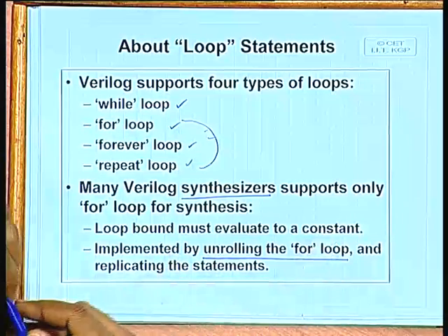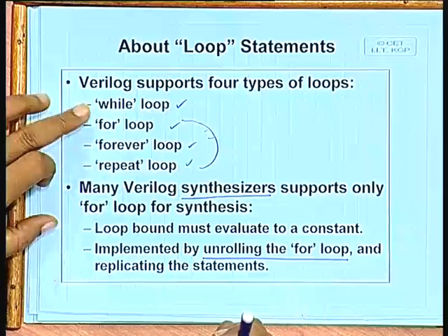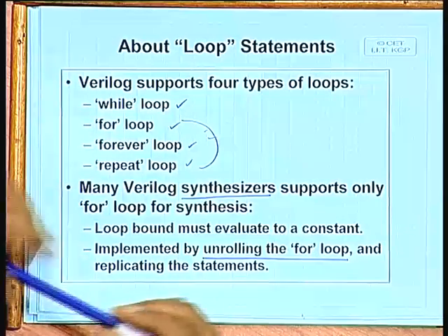So many Verilog synthesizers support only the for loop, which means they don't support the other three. These are fine for simulation, but when you are interested in synthesizing into hardware, the synthesizer can run into problems if you use while, for example.